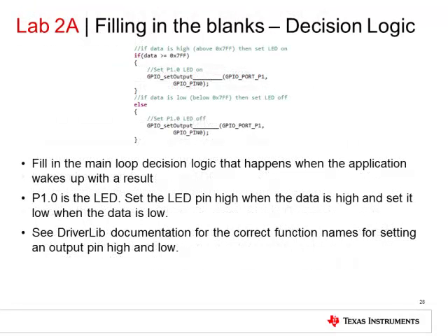The next step is to set up the decision logic in software. Remember, half AVCC needs to be expressed as a hex conversion result. You will also need to set up the GPIO port P1.0 to turn the LED on or off based on the conversion result. Once this stage is complete, we can move to the interrupt service routine.